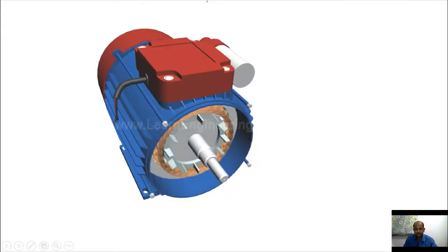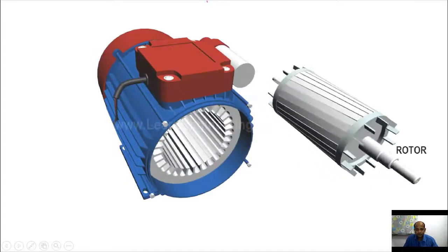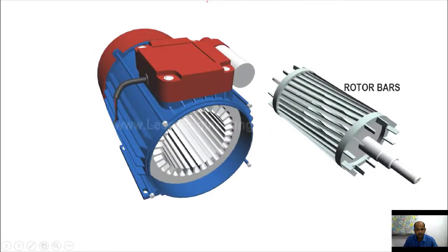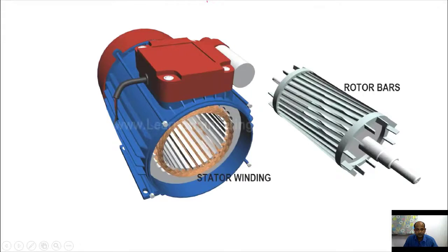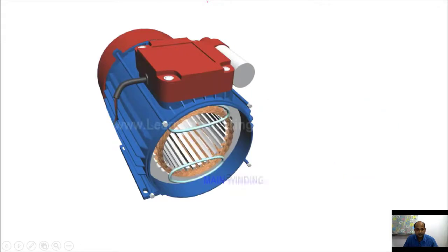So just a quick recall, so that you can understand what is happening. Here we have the rotor bar skewing, the stator winding, the main winding, and there is the auxiliary winding. Quick recapitulation: they are 90 degrees with each other. A capacitor is connected with this auxiliary winding to provide that initial starting torque.